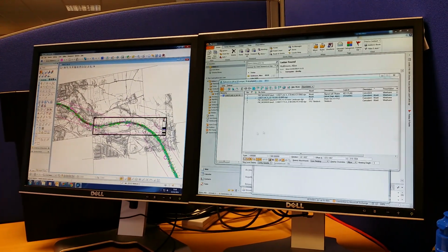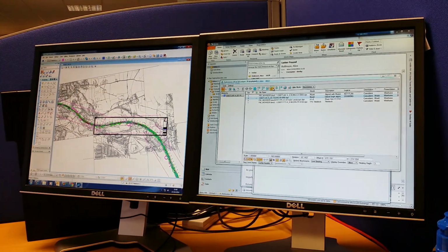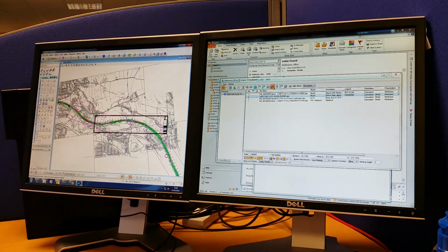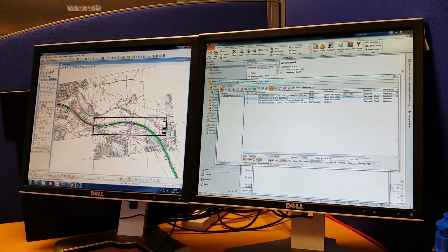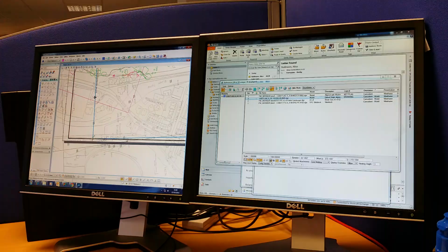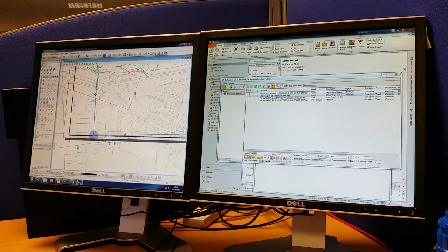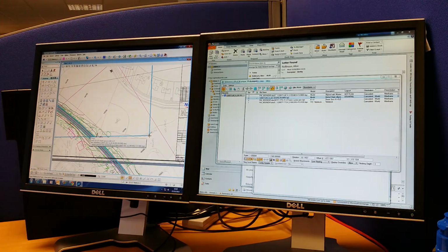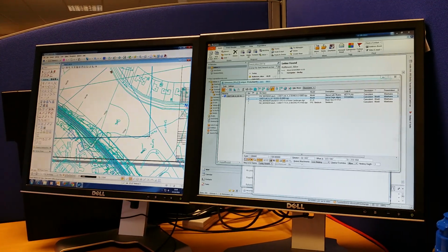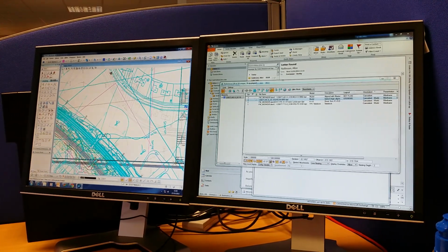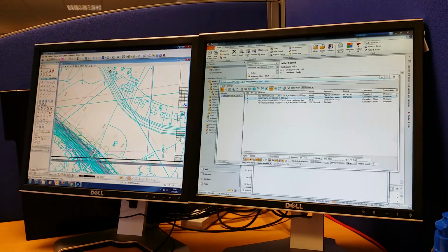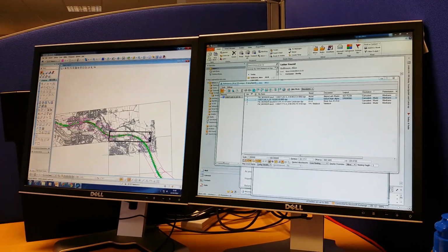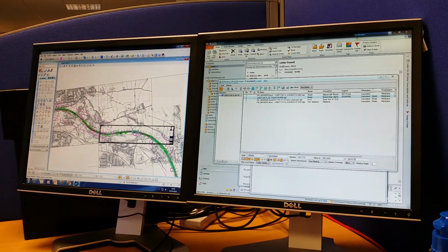While that's still highlighted, click on rotate reference, pick your base point that you're rotating about, and pick the end point that you want to rotate. So in this case it's the sheet, the view. Pick the next point, which is the sheet frame, and that's rotated it to where you want it to be.